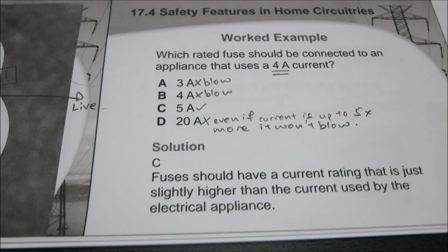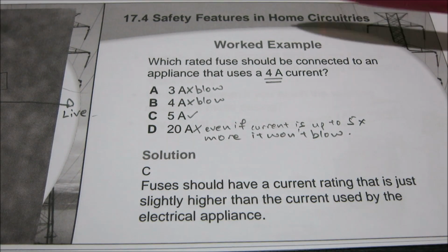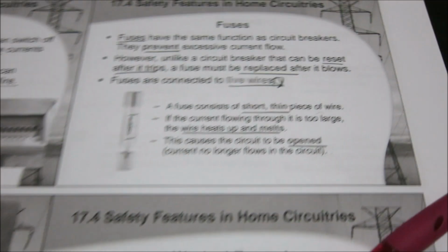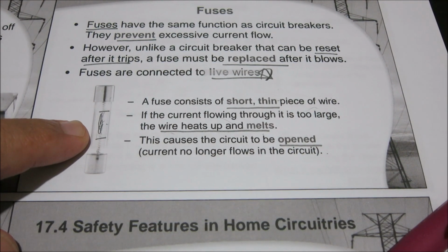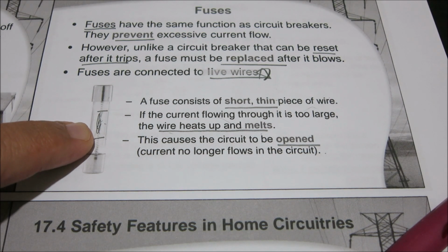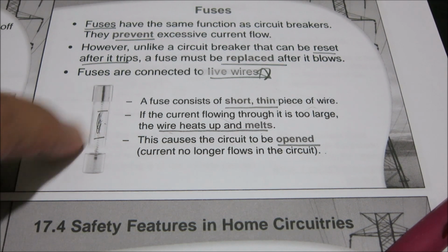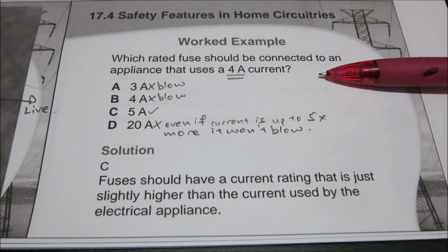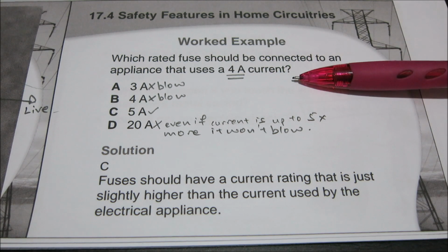Now, how do I know what rating of fuse to use? Basically, a fuse is just a short thin piece of wire. So the thicker the wire, the more current it can take before it melts. The thinner the wire, the less current it takes for it to heat up and melt. So knowing what kind of fuse to use is important for the kind of equipment you are using.